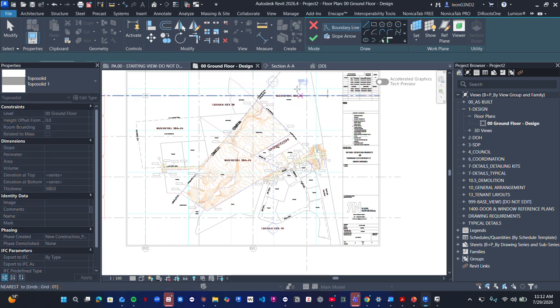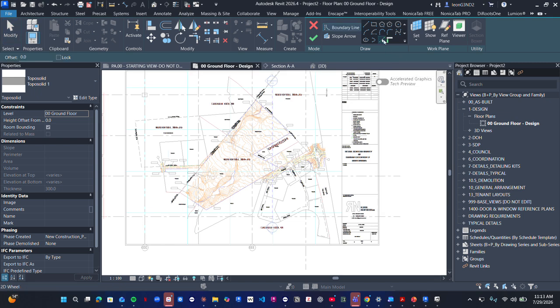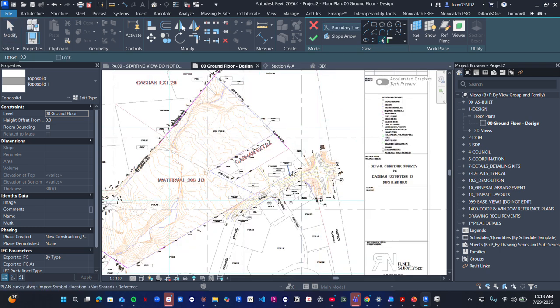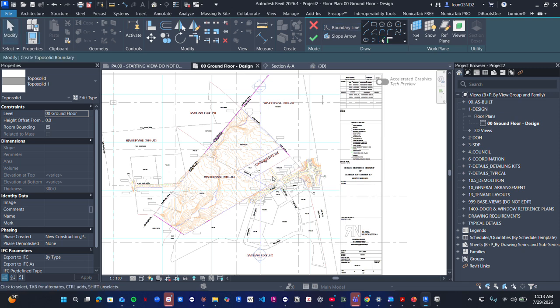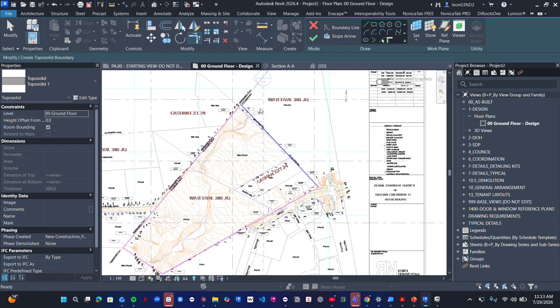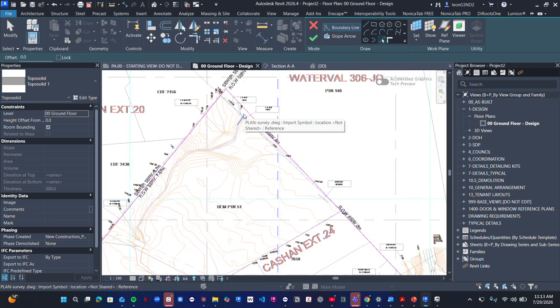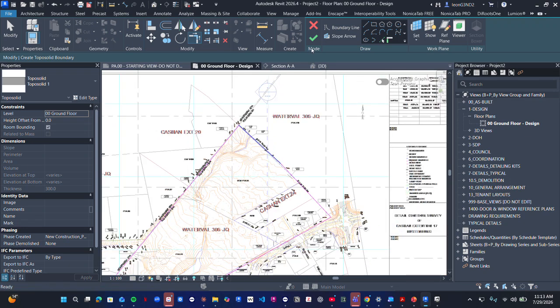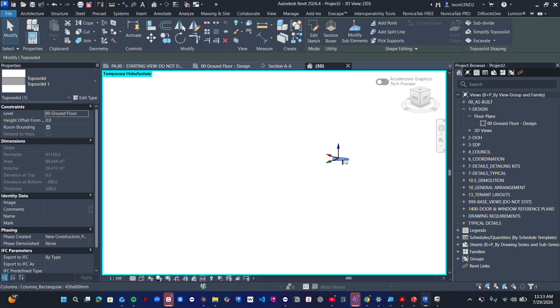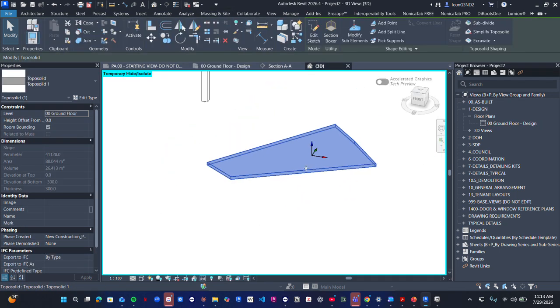Just here. You can also select this tool here, which is pick lines. So you can just do that there, that line, that line, that line. Then you can trim and extend, TR, do that there. Just make sure they align. Do that there. Just one more here, so it's a bit more accurate. Trim and extend these two here. There, and I say okay. See here, that is our site created.